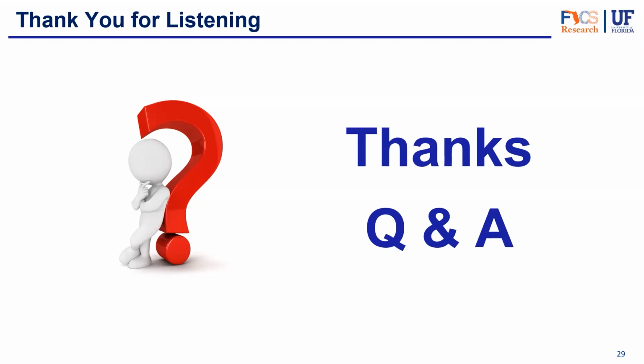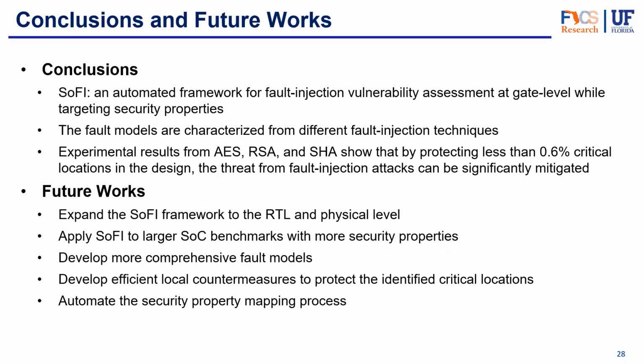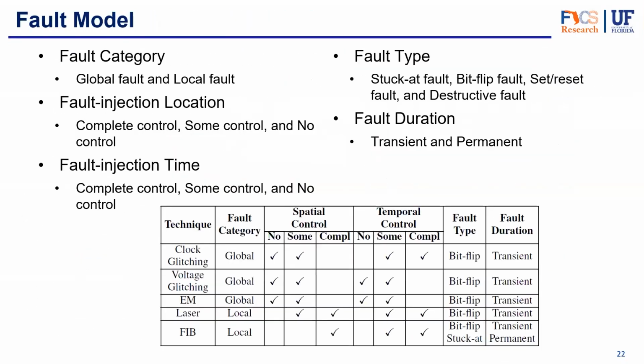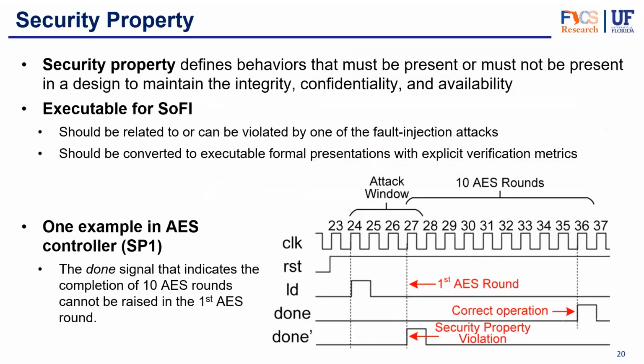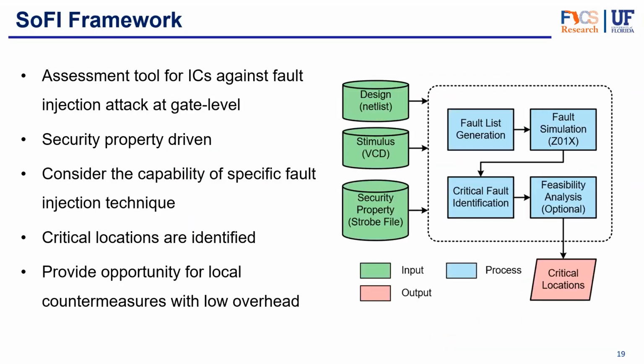Any transition. I need to explain a little bit. The fault simulation is based on creating a lot of random stimulus, and it does the fault simulation. Based on the current value that we have, we assume that the value will be flipped from 0 to 1 or 1 to 0, to see whether that property can be violated.